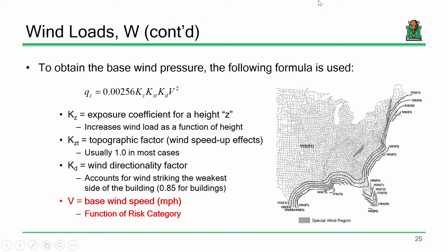Okay, let me say this. The question was, what's the deal with basically wind and piles? If you have wind striking a building, think of the building as one large beam. It's almost like a big cantilevered beam. So part of the building would be experiencing compression at the bottom, and part of the building would experience tension. So it's possible that you could have some uplift effects on your piles on this side of the building. But you also have to keep in mind we're talking about wind effects versus the massive weight of the structure. So that really probably wouldn't happen under wind.